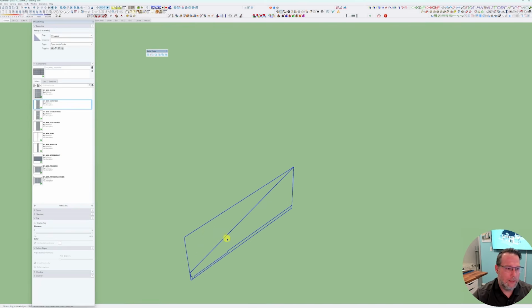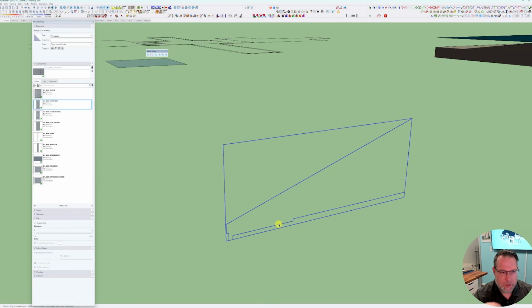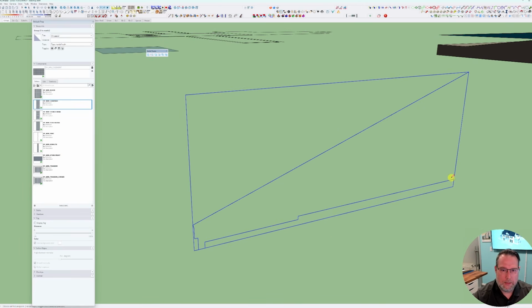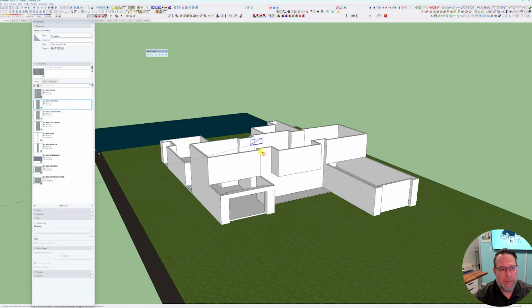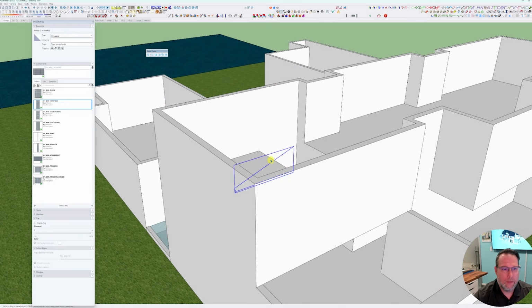So I have this outline here, and this comes from an actual AutoCAD wall section. I always create a polyline to where you can see the exact outline of where the truss would be and where the plywood would be and where my fascia would be. So this is a one-to-one of what my actual roof would look like. So I'm just going to make a copy. I'm going to bring it over here, and